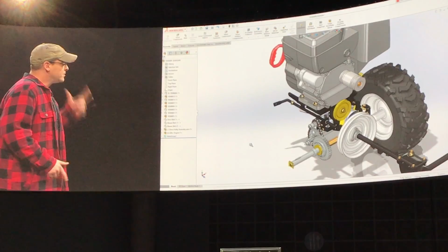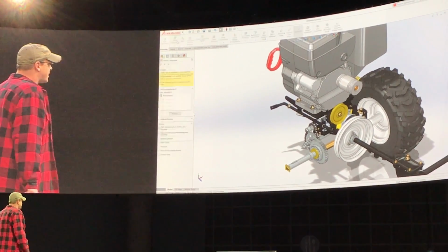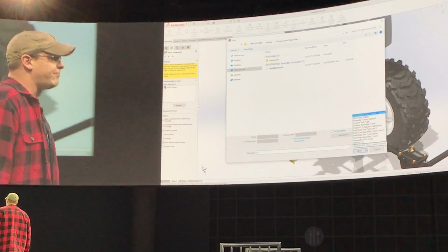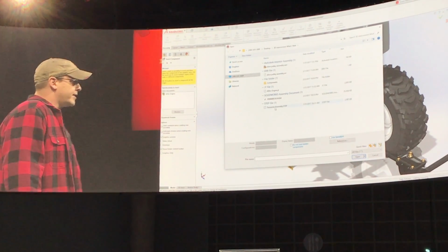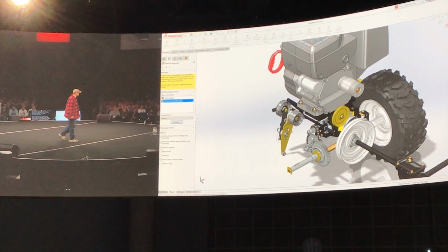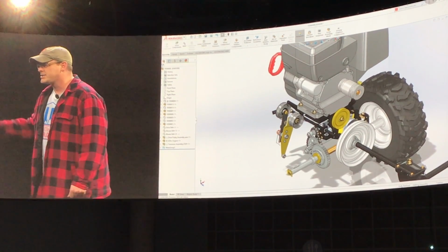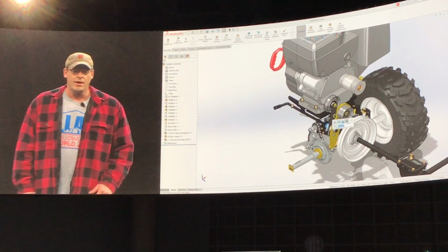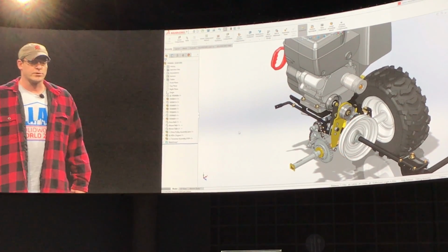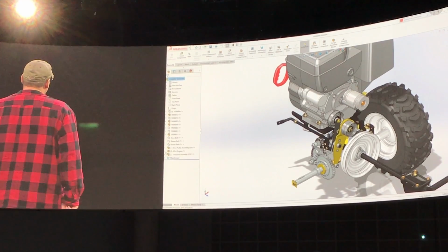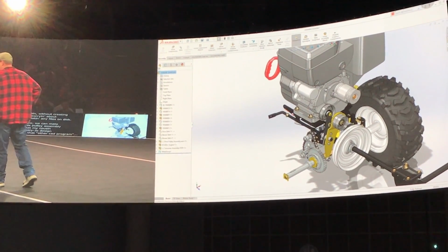That was excellent. Let's take a look at this snowblower that me and my cousin Jim Bob have been working on. We need to add a new assembly that's in STEP format. And with 3D Interconnect, we can now directly insert a whole bunch of new neutral file formats like STEP, IGES, ACIS, and even JT. And once they're inserted, they're treated just like any other SolidWorks file, meaning we can easily make it into place without worrying about creating any files on disk.